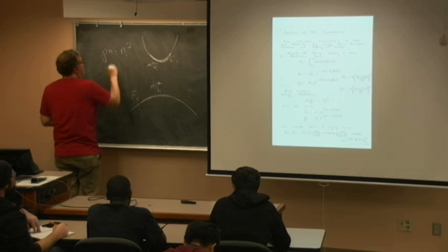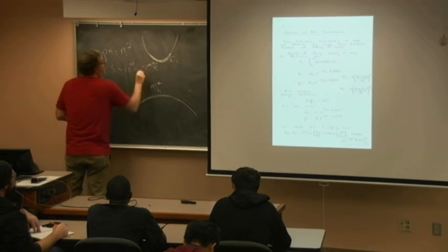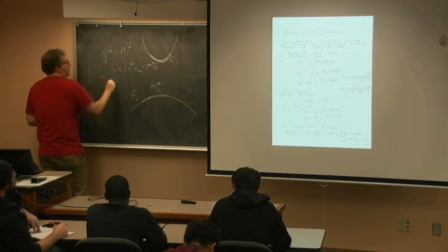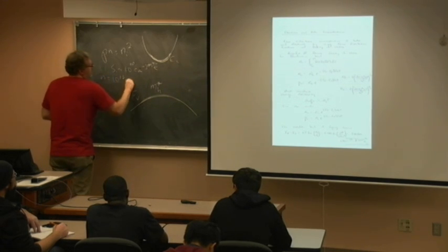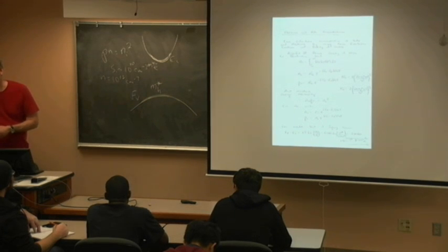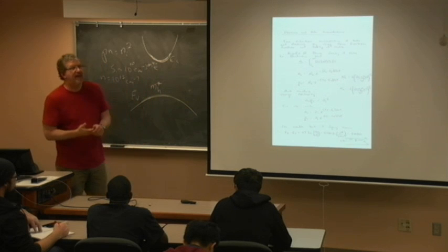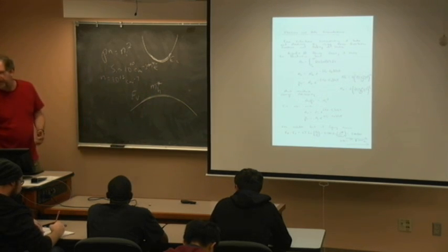If I said it was silicon, ni about 10 to the 10, and I gave you n-type doping of 10 to the 18, I would hope that you could tell me how many holes I have. 100? Yeah. That's as calculator intensive as you're going to have to do.